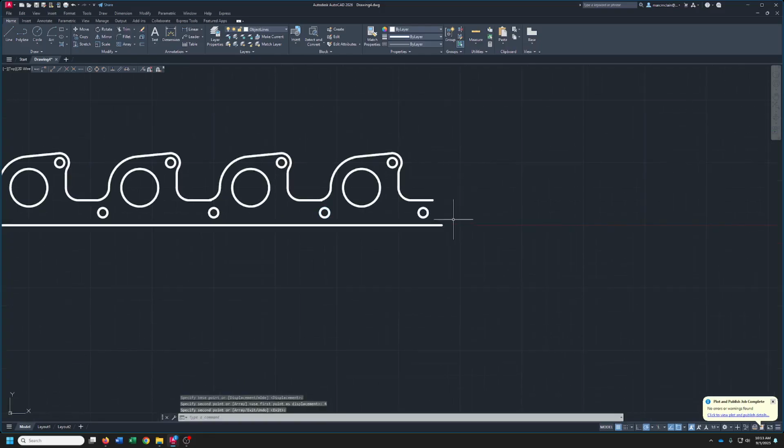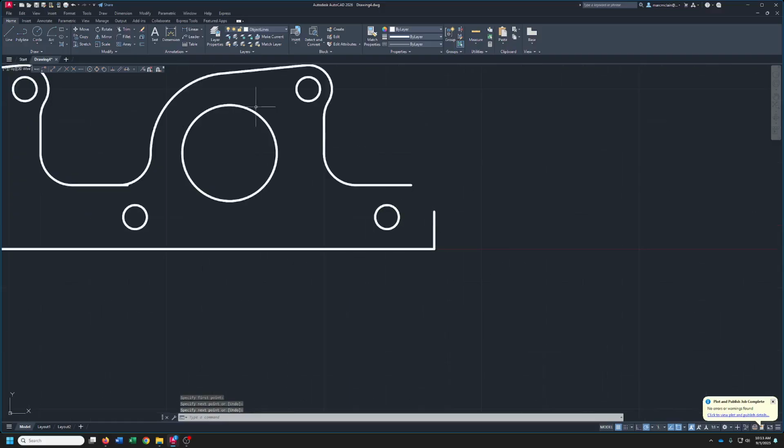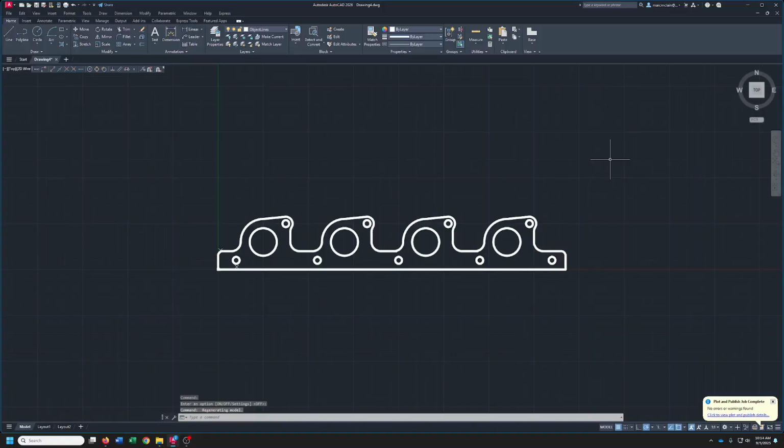Okay? Now, draw a line up. Doesn't matter how far, because you're going to fillet this. So we're going to get a fillet, and we're going to change our radius to 0.25. And we'll just pick and pick. Get our cube out, go top. Now it's centered. All right.